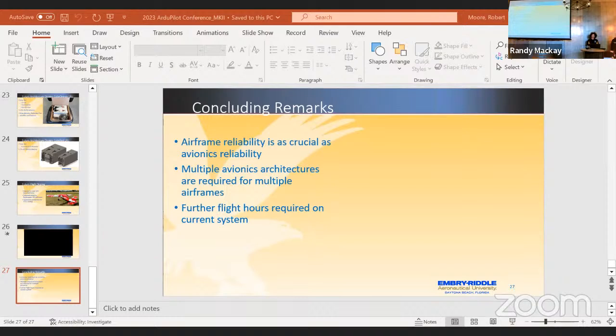But plane also tends to be a bit more point and shoot in its navigation. It doesn't have the tight position controller, it's got cross-track, and it'll probably handle a cross-track error being kicked in quite cleanly anyway. So you can probably get away with a simple Lua script just keeping those items set to 0.